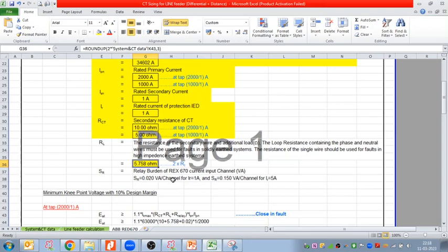If not, I'm ready to repeat all these things, because we already discussed these for the metering core. That's why I'm telling you that you can refer to the same discussion we had for the metering core. Okay, Mohammed, thank you. Yeah, lead resistance, correct. Congrats. The lead resistance depends on what cable, what size of the cable we are using, and what is the length of the cable. Based on that, we calculate the lead resistance, right?